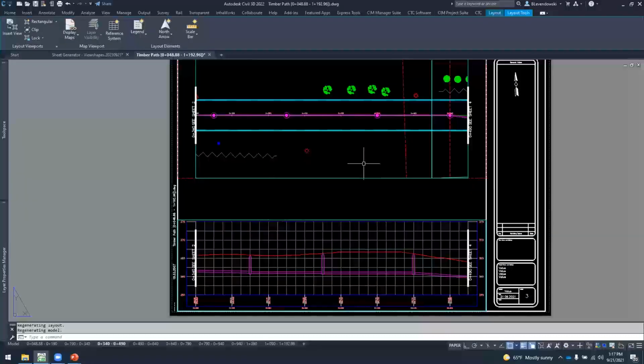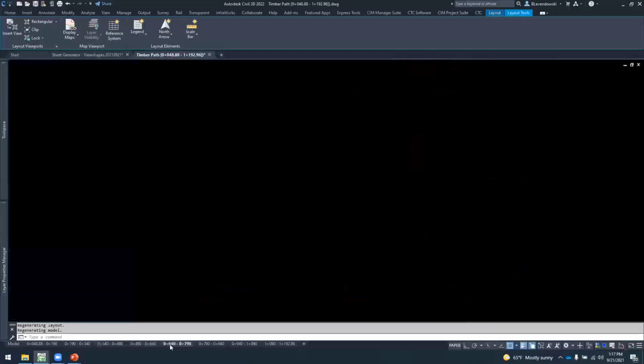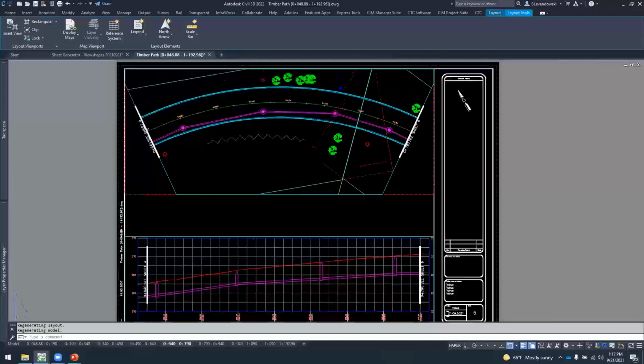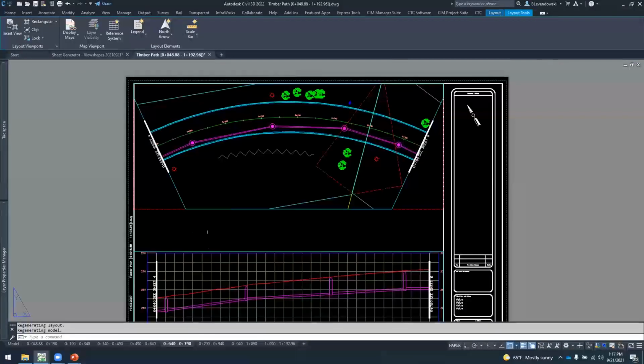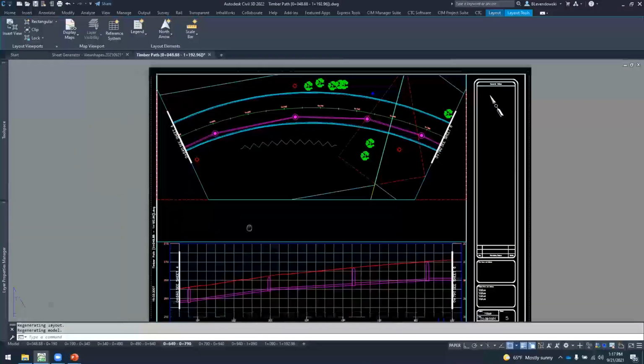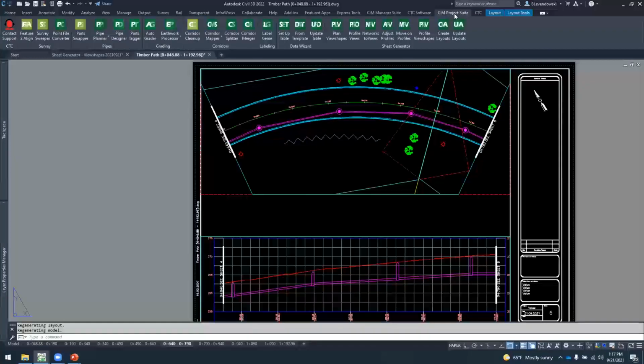And then here's what we're after, right? Updating our layouts. I've shown you a lot of enhancements and features along the way that improve the process and the workflow or the native tool set. But the crux of this is, how do we update layouts? And it's just as I'd shown you, use any of these modules to adjust any plan or profiles that you want in model space. Then run update layouts, which you could read as push model space changes to my layouts. That's basically what this command is.